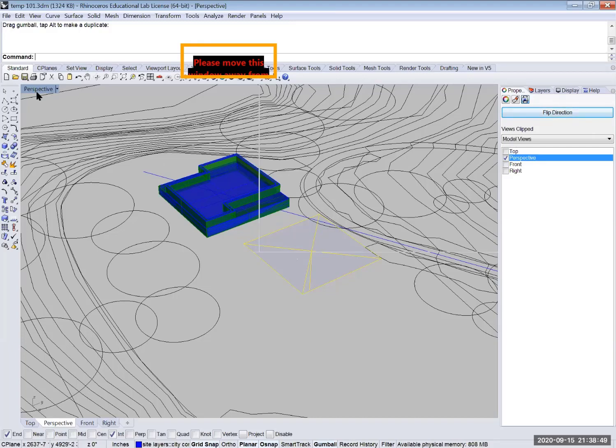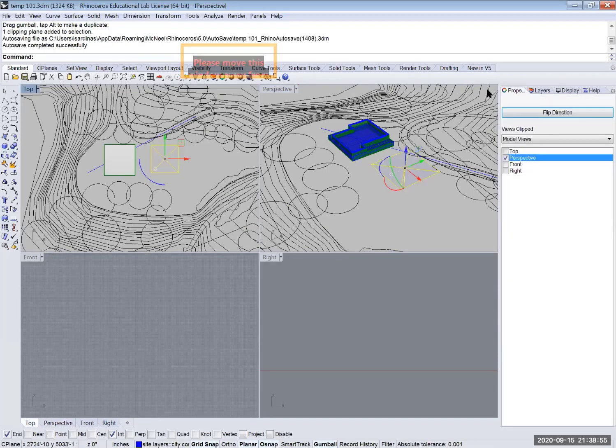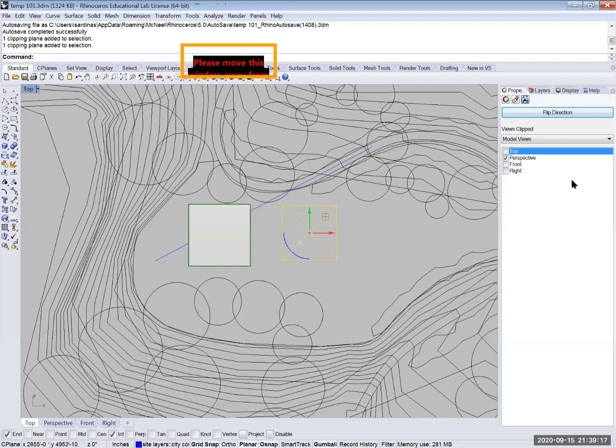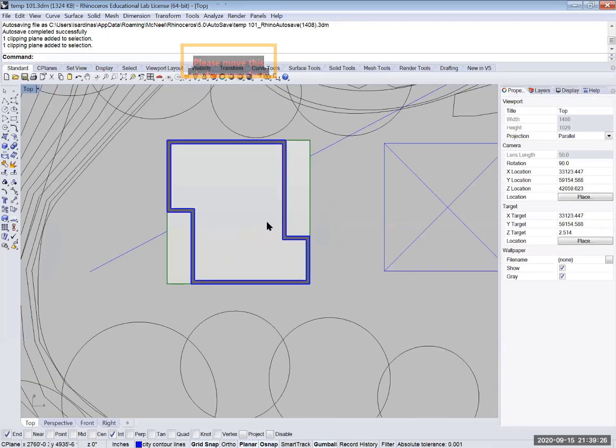Let me see what happens if I go to top view. I have to deselect the clipping plane and then reselect it. Hit the properties thing over here. There it goes. Okay, so there's my floor plan, of my clipping plane. You can see that I now have a much narrower distance here than my 30-foot cube. I could put my door here and enter into this small area. I could put my door here centered on that line that's coming in, the sight line. I need to have a door that comes out to my sunset porch, so I could put that here, or I could put it somewhere in here.